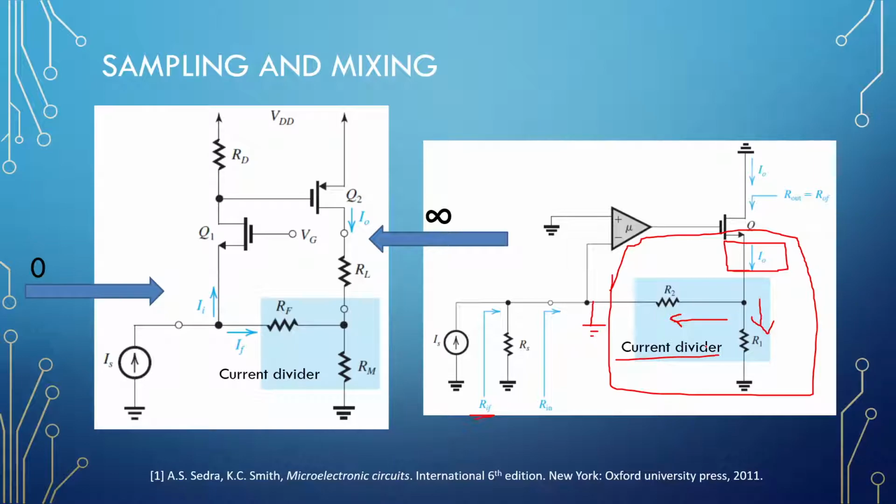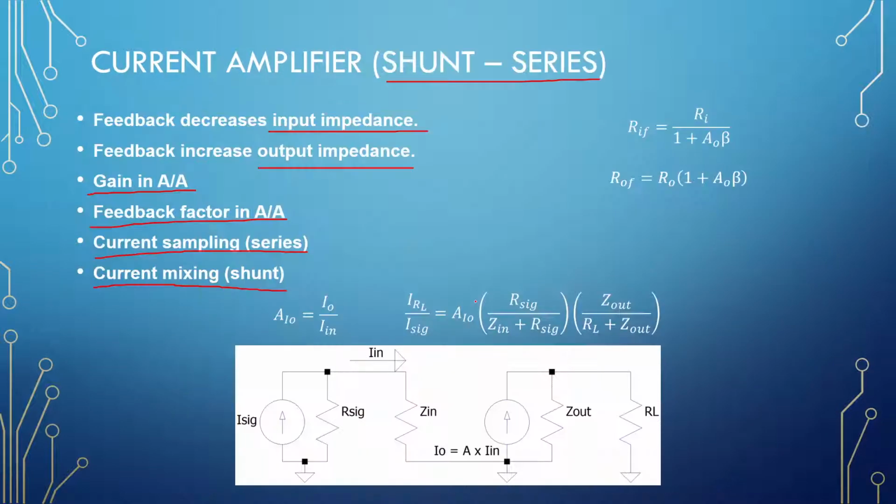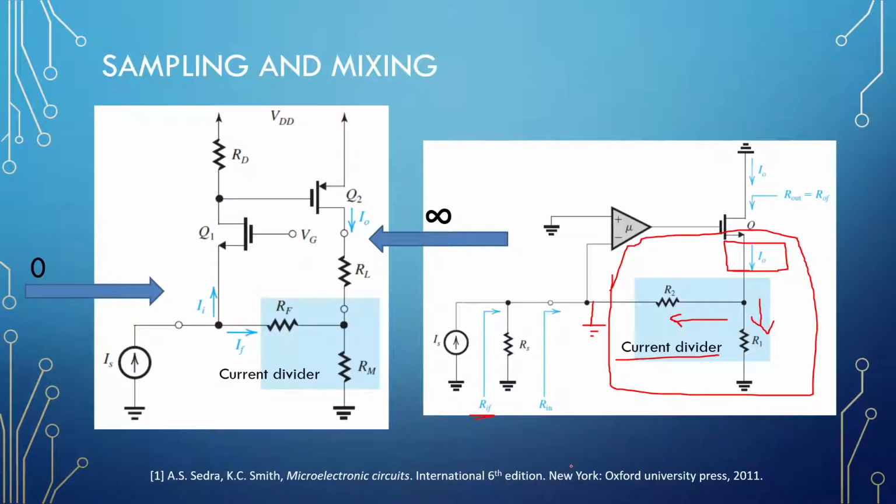So that is how we will treat our beta network, as a current divider. Also, when we are doing loading factors, we should also remember that we look at current division in our amplifier. Okay, so the loading factors is current division on the input and the output side.